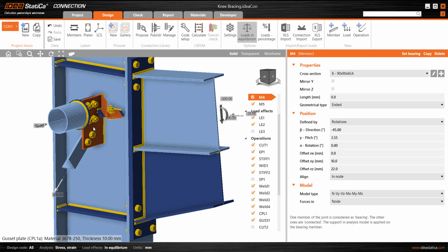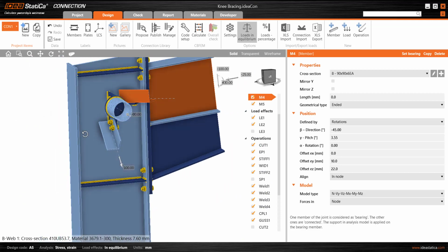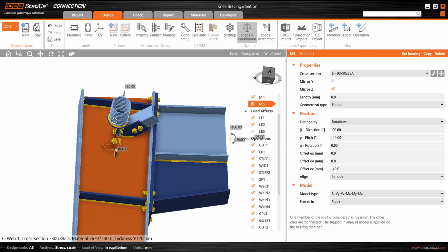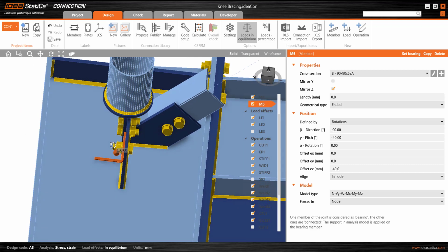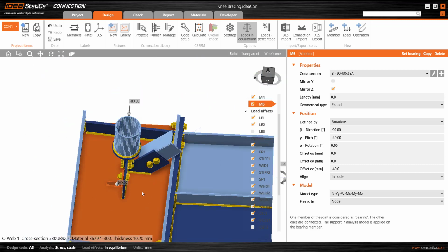And so I'm fairly happy with that connection now. But one thing to consider, particularly for bracing members with significant axial force and where a non-symmetrical section, in a sense, or not fully symmetrical, such as an angle, is being used, and we're connecting to a leg which is not at the centroid. We've got the tension. The axial force is applied at the centroid of sections in all cases in the software, and similarly with other actions such as shear.